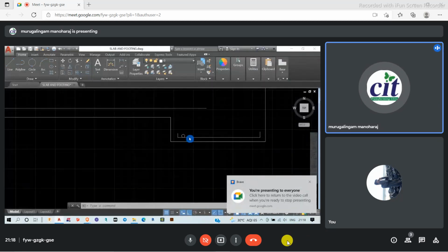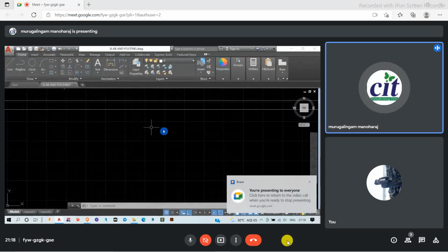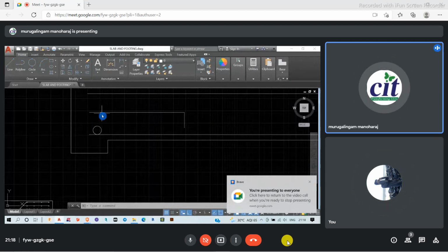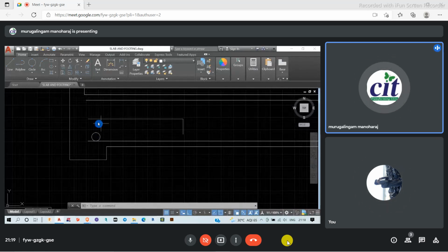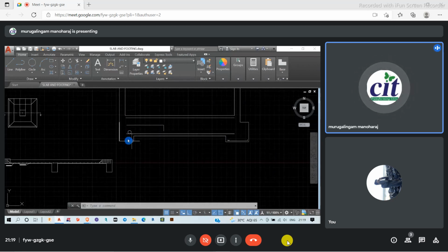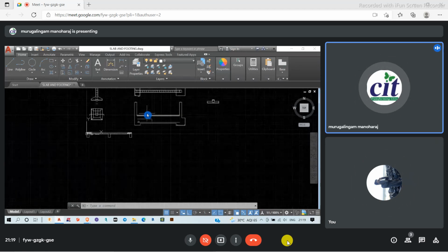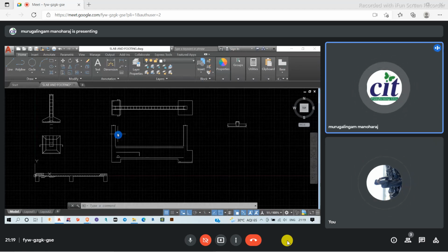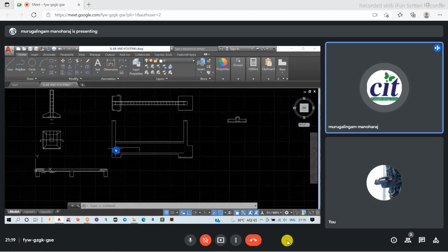So in this way, normal reinforcement is provided here, but here the reinforcement will be provided in the form of a strap beam. That's the difference. In one direction, we will be providing normal reinforcement. In another direction, the reinforcement will be provided in the strap beam, which is going to carry my load here. That's the different kind of orientation which will be provided here.